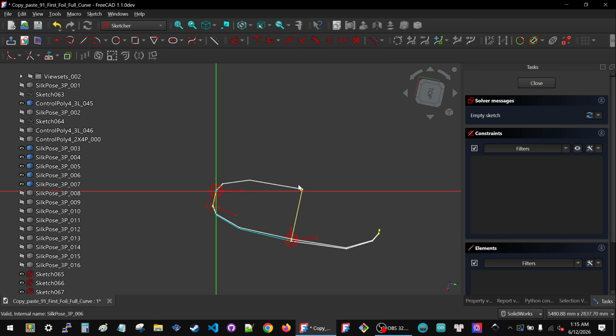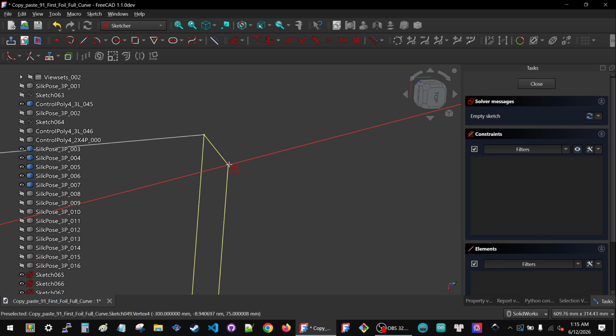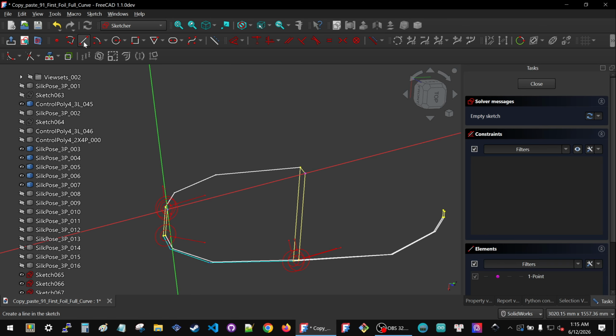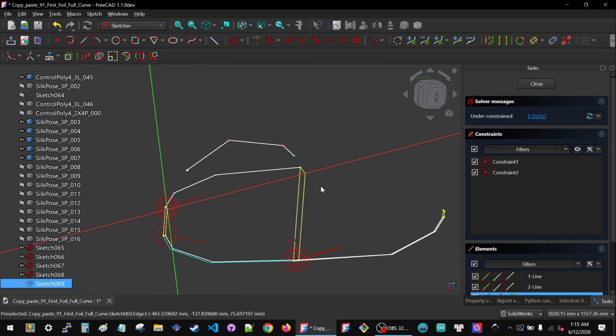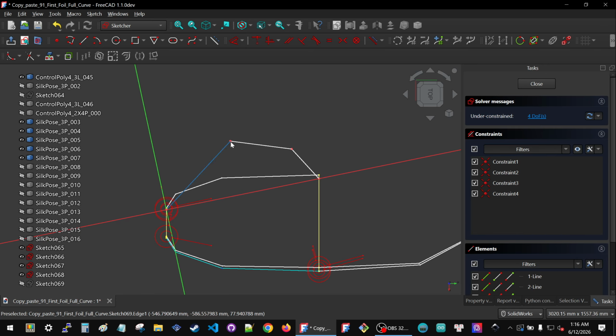It's the guy right above. Sketch, objects XY, right here. Import just this reference geometry. A vague three-line. Window select, coincident. Window select, coincident. Keeping the sketches simple makes this possible. Right? If I had too much reference, too much stuff, it would be a pain to find the origin and to find these things all the time, especially because FreeCAD makes it really difficult to exactly click on a point and have it assign the correct reference.